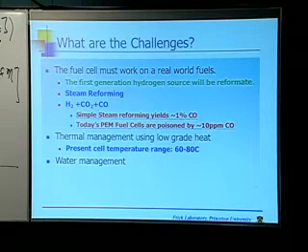And we all know CO is bad news for us. It's really bad news for a platinum catalyst. So we have 1% coming out in a simple reforming stream. The fact that these systems I'm showing you can't really tolerate more than about 10 parts per million of CO in the hydrogen stream. They poison at 10 parts per million over a matter of a few hours.